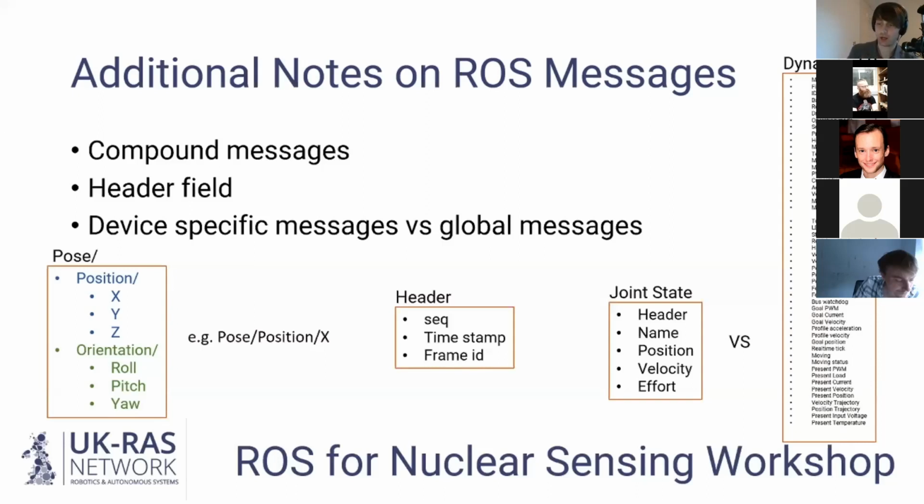A common servo motor that's ROS compatible is the so-called Dynamixel servo, and that actually sends two different types of messages at the same time. One is its own message, a Dynamixel servo message, and you can see that has 51 fields. It's massive. It's clearly a lot of information that has to be sent every single time.